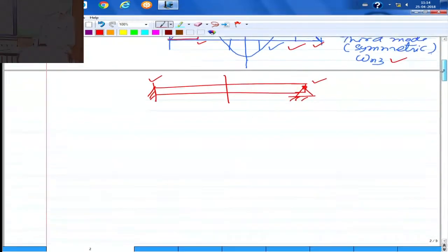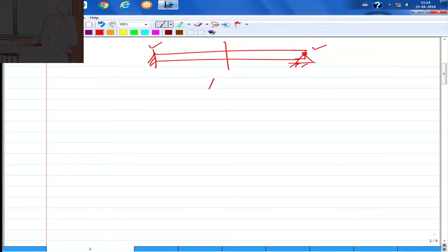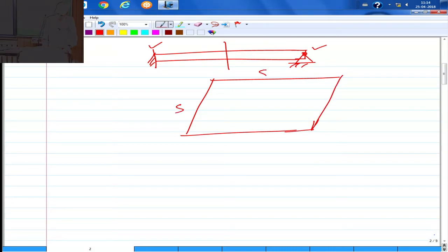So in this you won't be able to classify the modes into symmetric and antisymmetric modes. It is the same thing if you consider, say, a plate structure, where you have similar kinds of modes. Let us say all the edges are simply supported, that is, transverse displacement is 0 and rotations about the tangent are allowed. So it can rotate like this, it can have a non-zero slope about these lines.